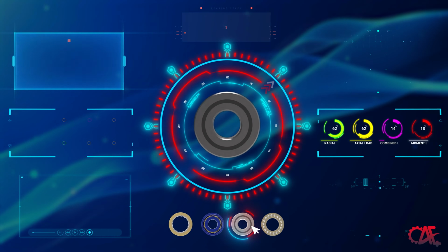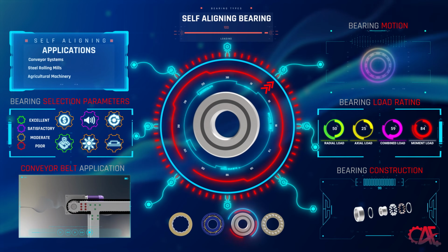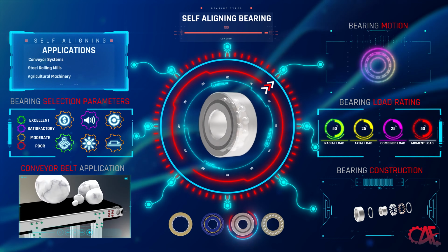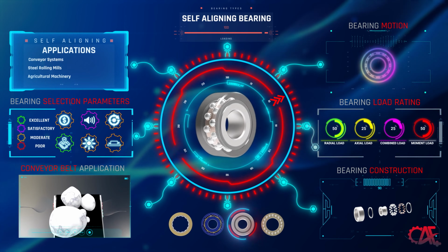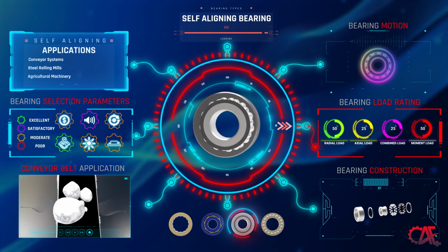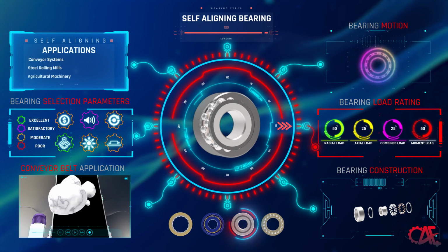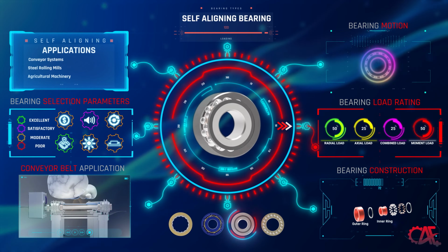For our third bearing selection, we will introduce you to a bearing type with some distinct characteristics. Self-aligning ball bearings demonstrate a unique advantage in situations involving shaft misalignment or installation errors. They offer moderate radial load capacity, but have poor performance with axial loads, which also applies to combined load situations. The self-aligning bearing can handle minor to moderate moment load.